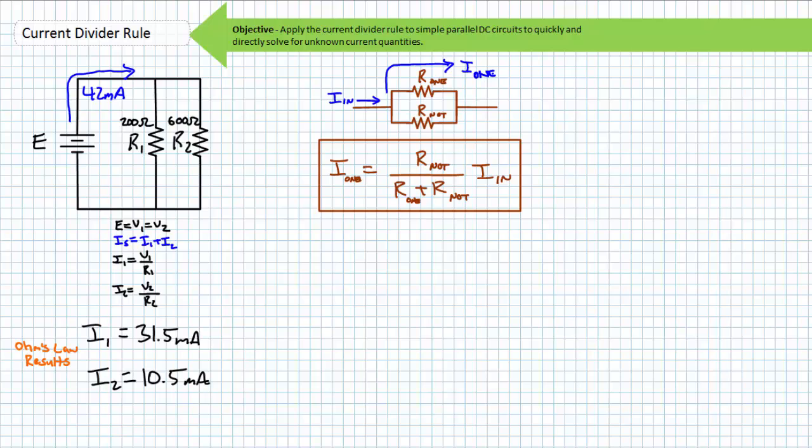Notice I am not using numerical subscripts for the general use formula, nor does this general use formula necessitate solving for total resistance anymore. That's the point. You'll save time, and if you have a modicum of organization skills, you won't get a wrong answer. The mathematically astute among you will realize that the CDR is a proportionate distribution of incoming current, inversely in proportion to the resistor's magnitude. The smallest resistor should draw more current. The larger resistor should draw less. Regardless, all incoming current is divided between these two resistors, no more, no less.